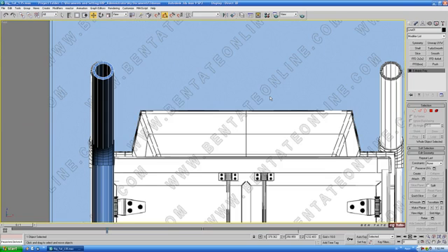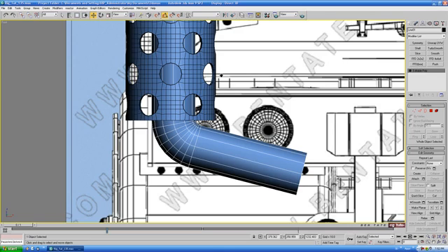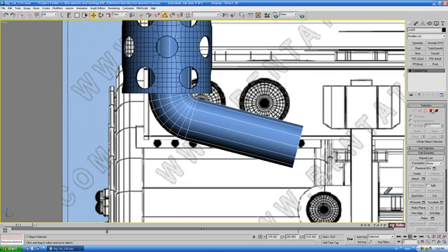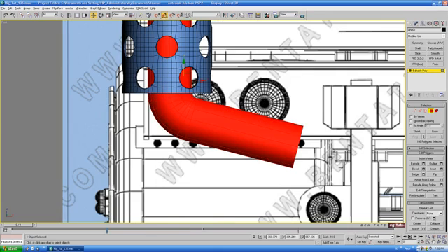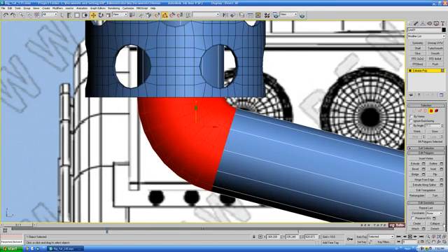And we'll do the same thing down here at the bottom. Go back into polygon, grab these polys here, and just deselect these ones and the side ones. Okay, we'll detach that as well.